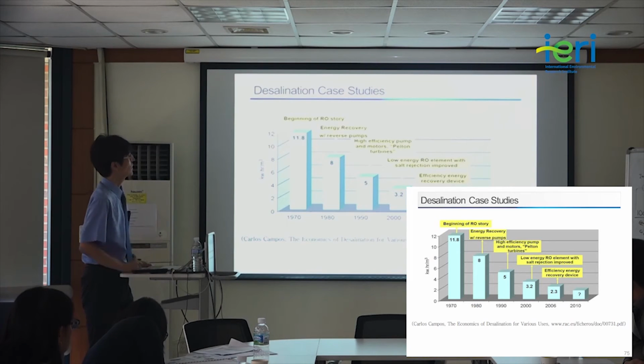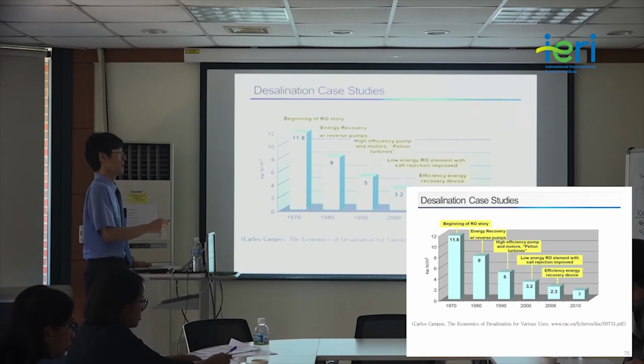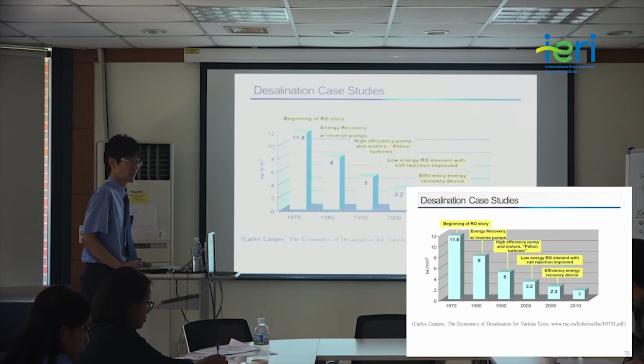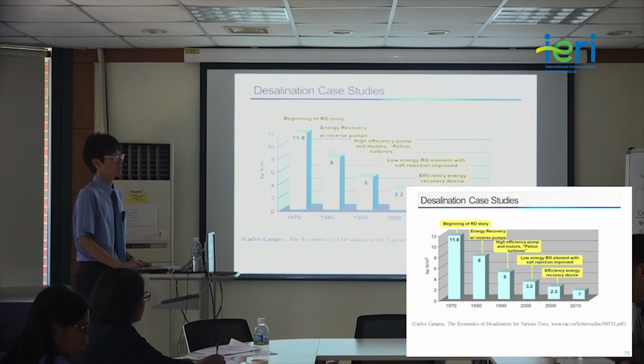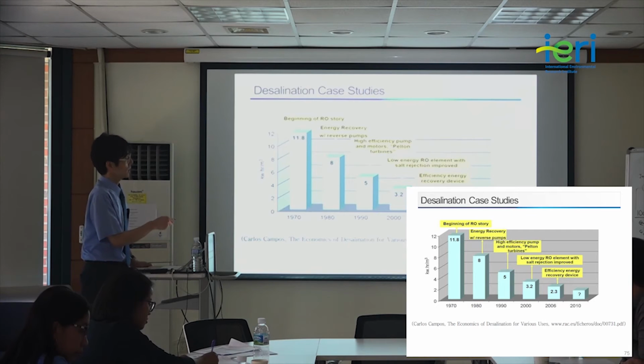And during this time, there was a significant development in reverse osmosis membrane. Low energy reverse osmosis membrane was introduced in the market, and the salt rejection was improved. So people did not need to consider multi-pass reverse osmosis membrane. So that's another reason for additional energy reduction.